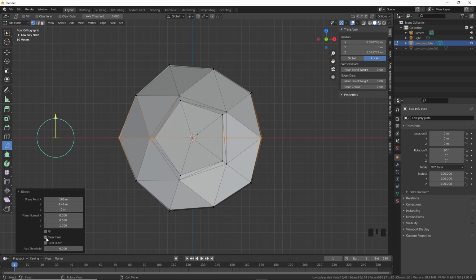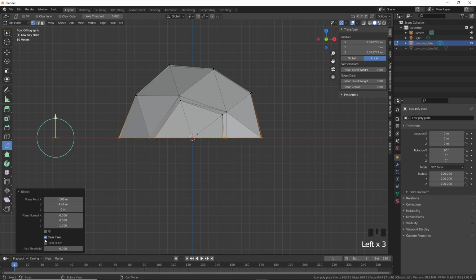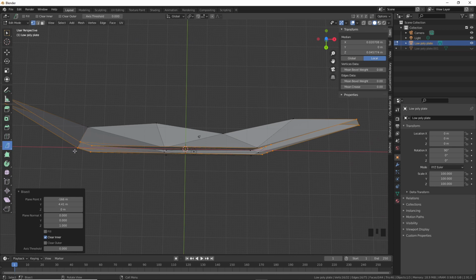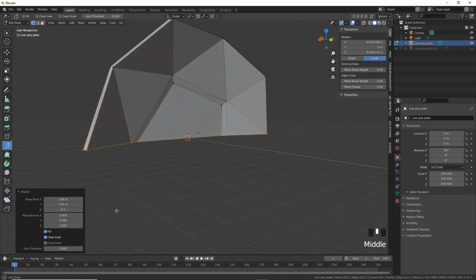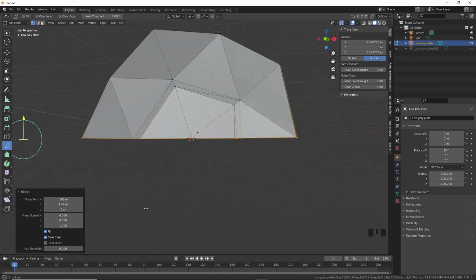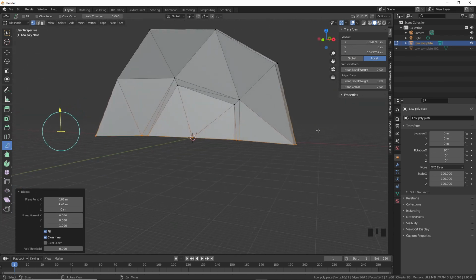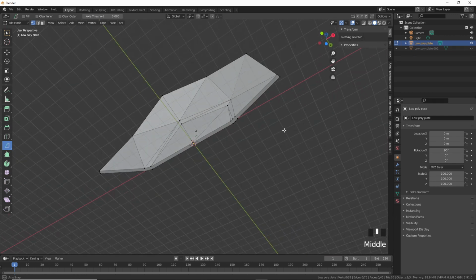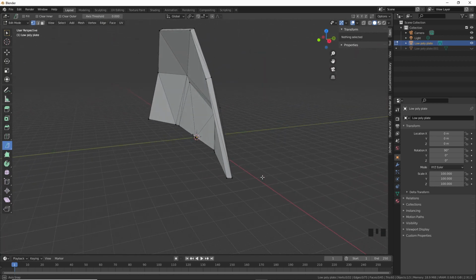So what I'm going to do now is select which one I don't want to keep. So let's say in this case I don't want to keep the bottom bit. So I click on that icon there. Now if we look here, you can see it's still open, and we can close it if we want to by clicking on the fill icon. Okay. So now we have closed our plate, and I'm happy with everything, so I can just click somewhere in my screen and then the command gets executed.